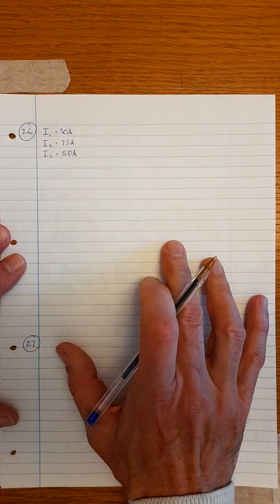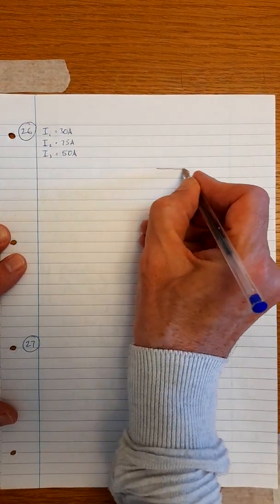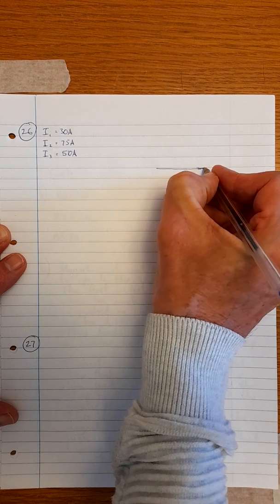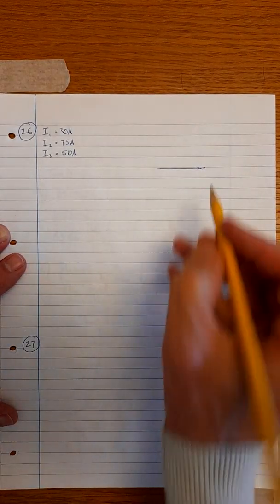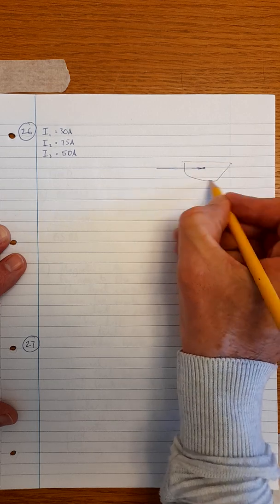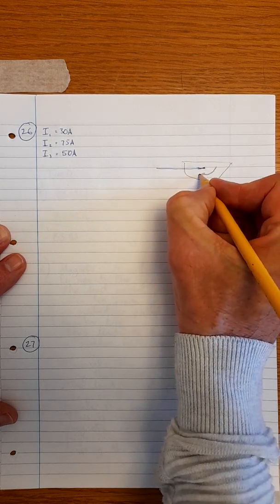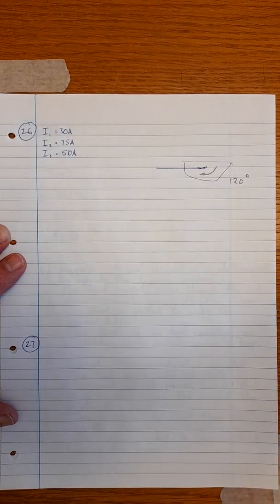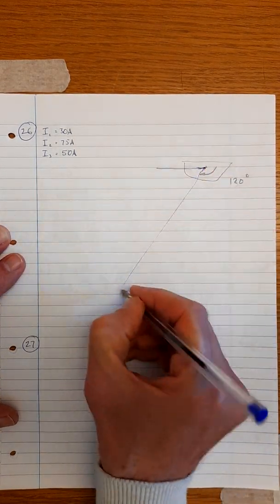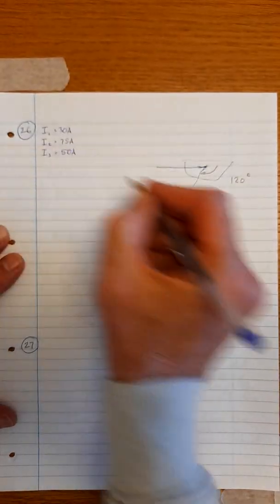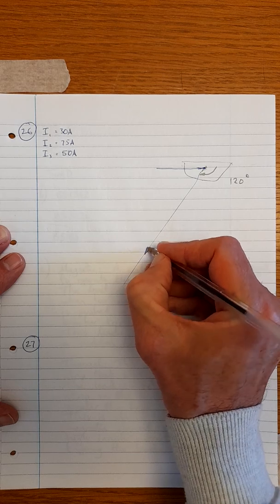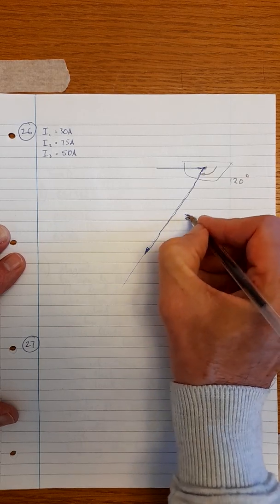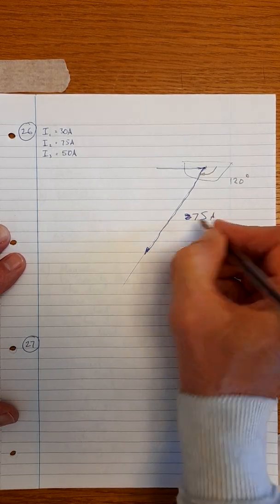I1 is 30 amps. I'm going to do this freehand. So 30 amps, you're going to do a line probably 3 centimeters long for 30 amps. So that's your first phasor. From the end of it, which is right there, you very carefully and accurately place your protractor on there, and you're going to measure around. So it's going to be upside down like that. There's naught. You're going to measure around 120 degrees. And at 120 degrees, you're going to do a line down there. And we want it to be 75. That's I2. So you measure 75. There it is. So that now scribbled in untidily. Oops. Sorry. 75 amps. That ends there.